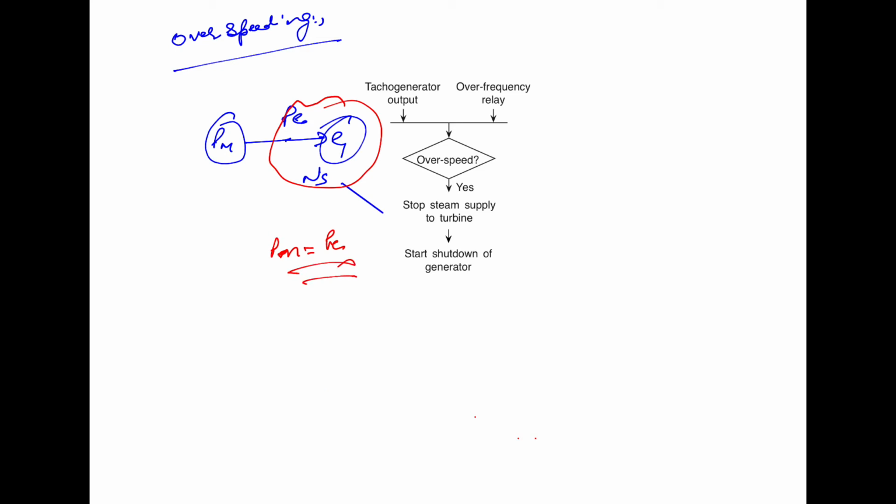It is disconnected from the grid, so the mechanical power cannot be suddenly reduced to zero. So we'll end up in a situation where the generator has a full input mechanical power but no output electrical power, and it will accelerate to dangerously high speeds, if the mechanical input is not quickly reduced by the speed governing mechanism.